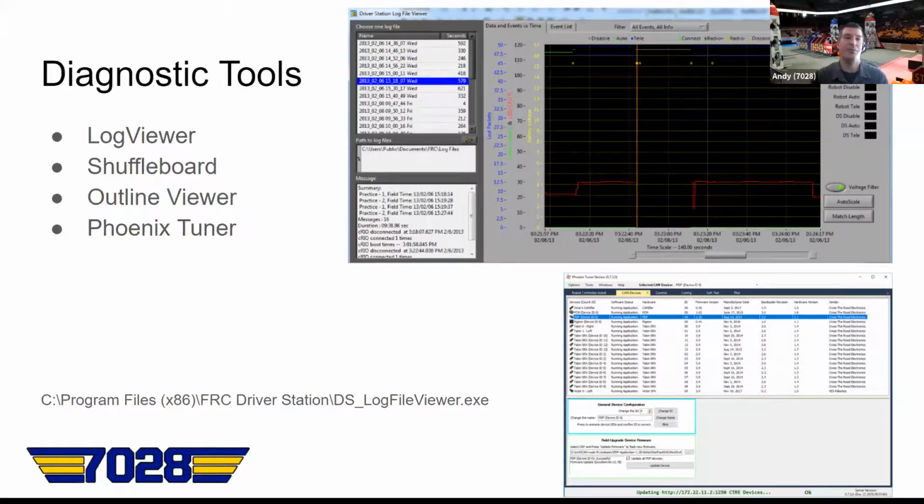So one of the things that we have to do when we install encoders is make sure the encoders are in phase with the motors. So when our motor runs forward, our encoder values go up. The plot makes that really easy to see. You open up the plot, you make sure that you can see your encoder and the output, and you run the motor. And if those two lines go up together, it's right. If one line goes up and the other line goes down, then you're out of phase and you need to flip those around.